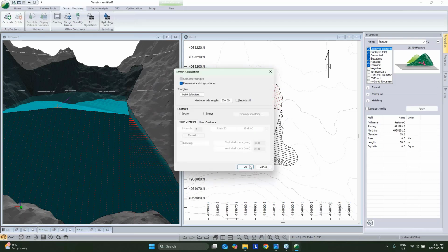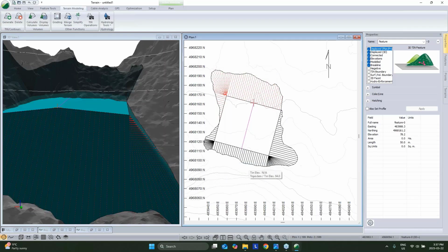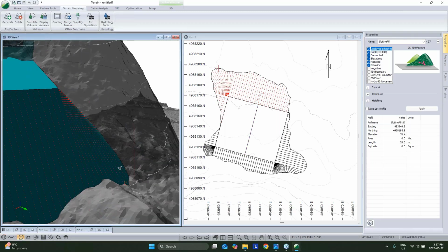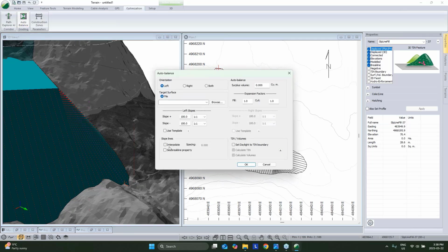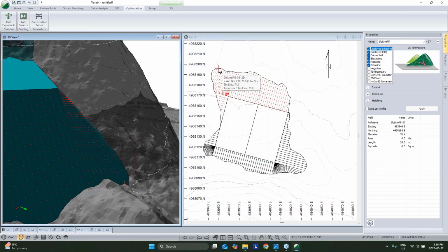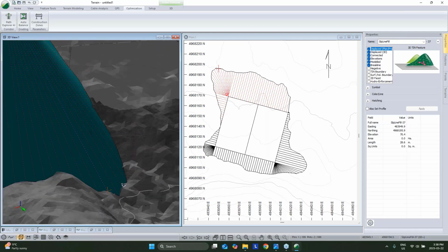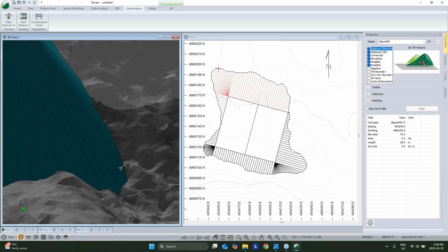So I used a break line to set my crown. Now that's not the only spot where the break line property comes up. On these slope lines, I turned on a break line. That was done in the slope lines text, where I told it to apply break lines. So down at the bottom, we don't have triangle interpolation going from that point to that point.